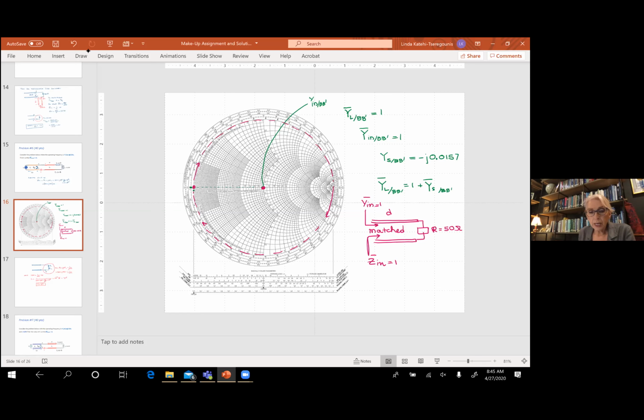So practically, you want to make sure that your admittance, when it comes there, is 0. All right. So the total admittance is close to practically 0 there, if not exactly 0. And that gives you the value that you need to have at that point, the length. And from that, you find the length of the stub and the length of the line.